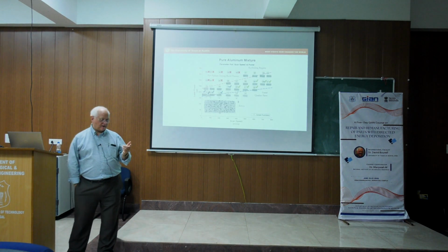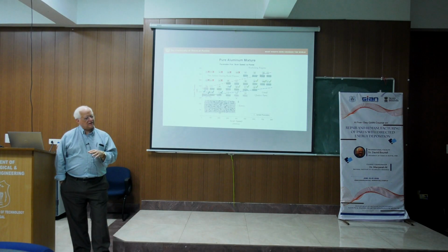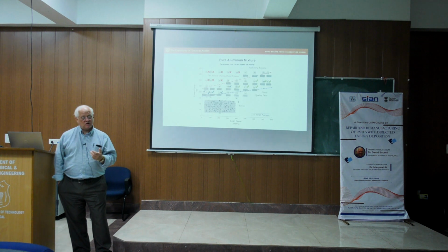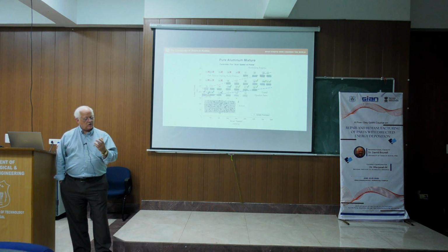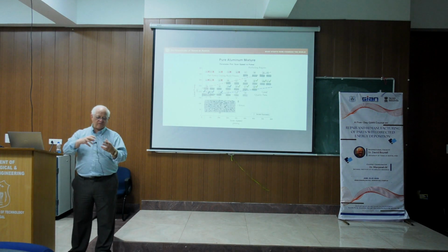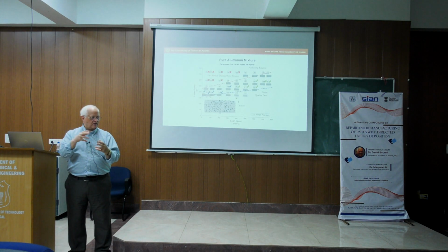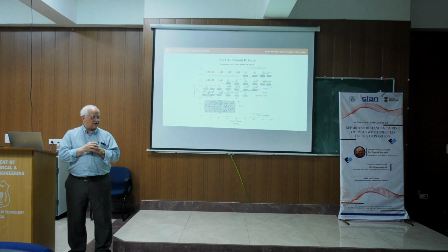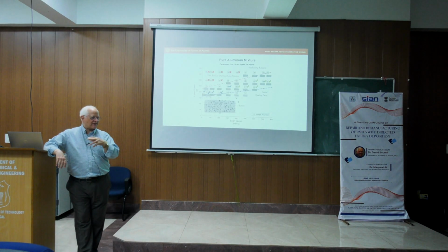There is a second type of anisotropy, but it doesn't really apply so much to DED. There were, and I think maybe still are, some systems where we can produce a porous skeleton of metal that is then back-infiltrated with something else. If we have a Z distinction in that structure, where we have, say, a high density in the plane but low density in the Z direction, that can manifest itself in the bulk part after infiltration. But again, I really think that's probably not much of a factor.